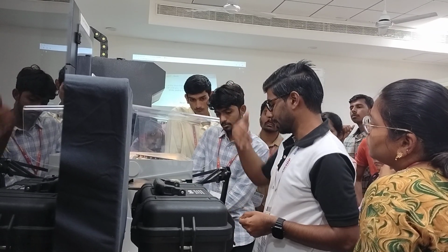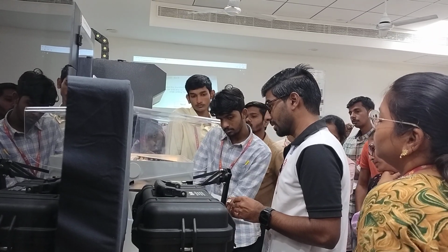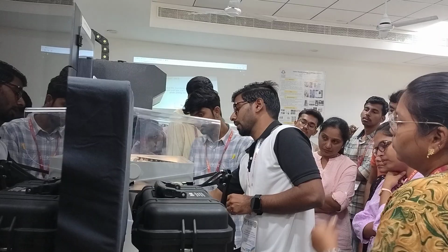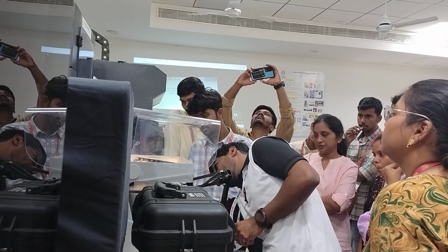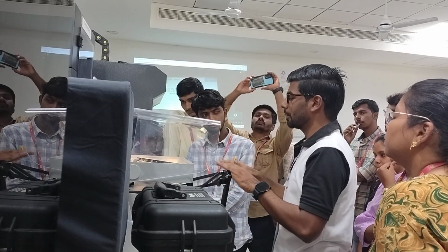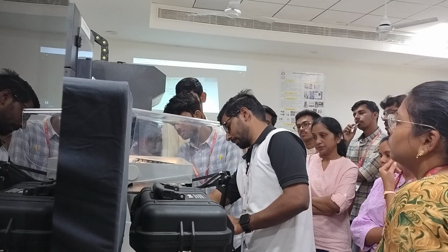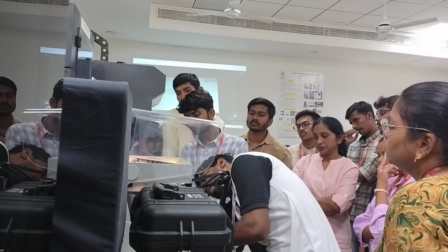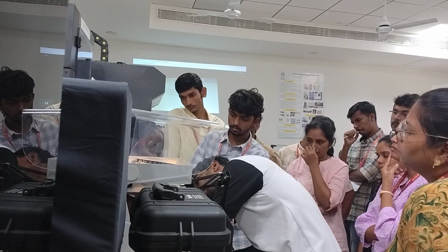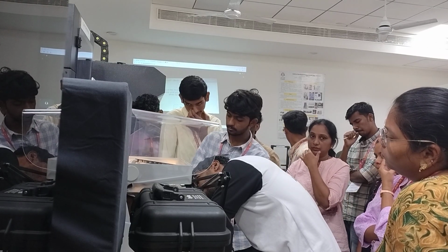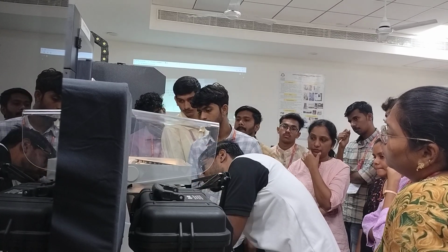Moving to the back position, that is the front, that is the back. Again, it says the same thing I have to do there also. So for making a plane, how many points are required? 3 points are required. If I adjust in 3 places, definitely my whole plane will be adjusted. The whole bed will be adjusted. I feel that this is a little bit tight, so I loosen it. It must be just resistance.